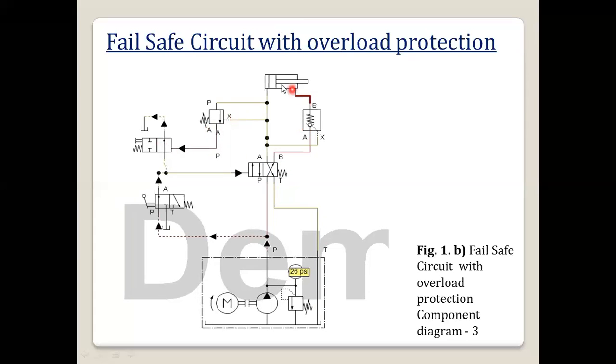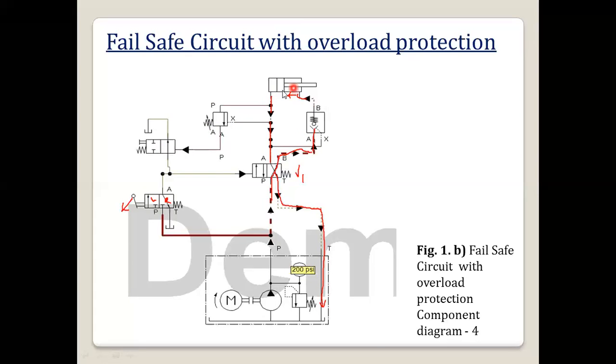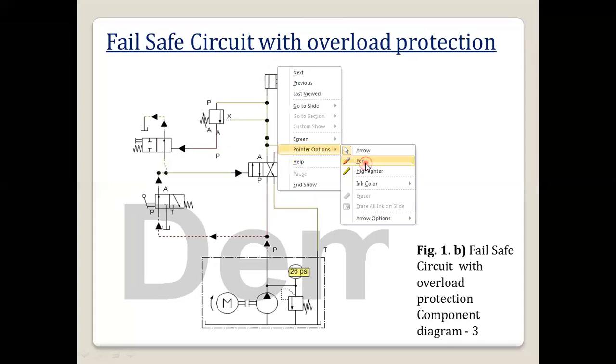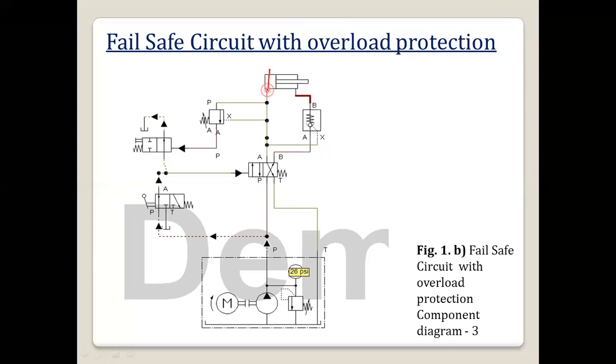Okay, so here this is the complete, here you have seen this is retracting. Okay, so here what, it has fully retracted. Okay, here it has been fully retracted. It has fully retracted, right? So here what will be happening? So this sequence valve will be operating. Okay, so what will happen from the closed position? From the closed position, that is, from left envelope to right envelope, which one will come? Valve 4.